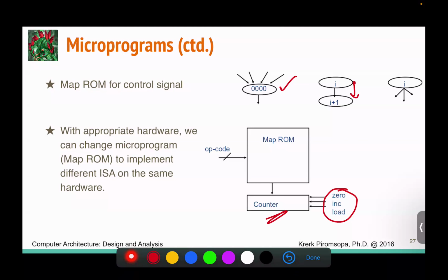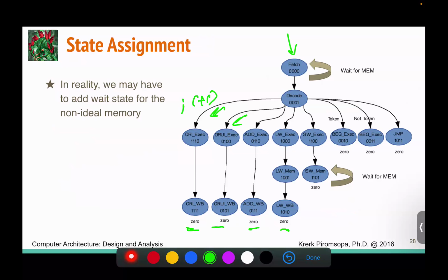So we basically say reset zero, go back to the beginning. For each line, it's basically increment of +1. Only time that we want to jump to an arbitrary state is load, L. So this is just +1, +1, +1. Only this one that you would use load. And at the end, you just do zero to jump to the beginning.